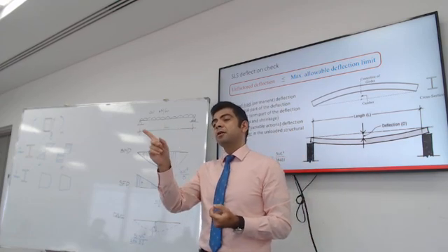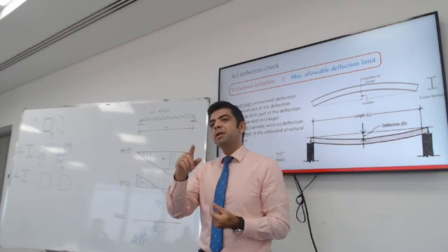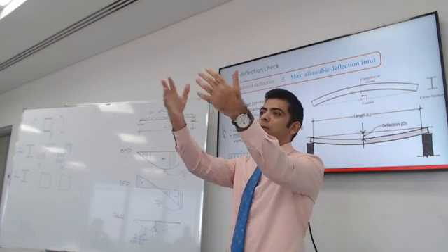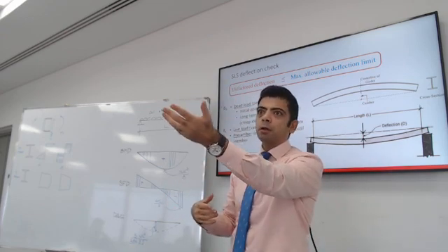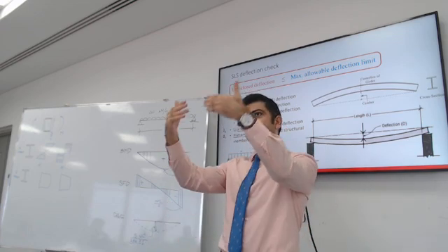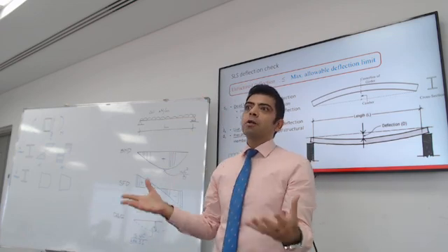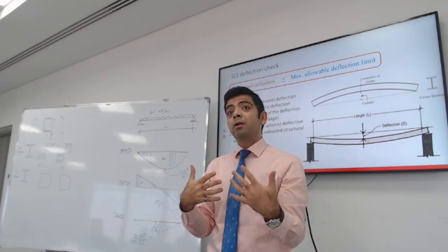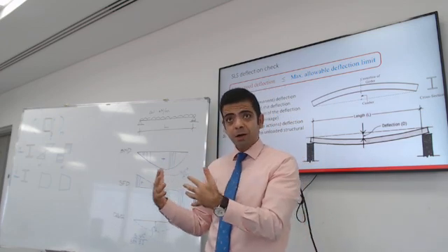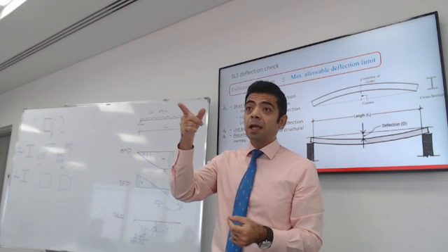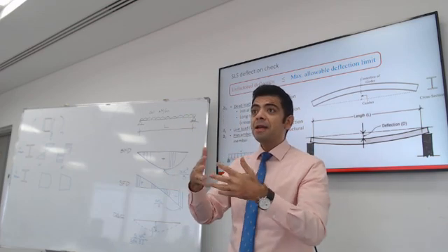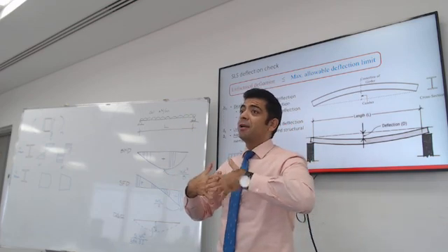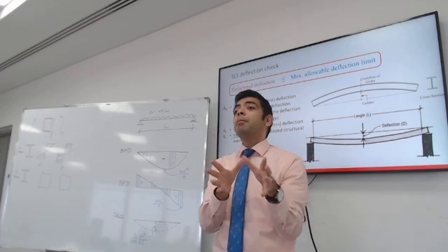Some designers, architects, companies will ask for the windows to be like a curtain wall. Like the entire facade of the structure is windows. So you hire someone to fabricate these windows. The fabricator of the windows will communicate with you, the structural engineer, that the maximum deflection their window can take is that much.